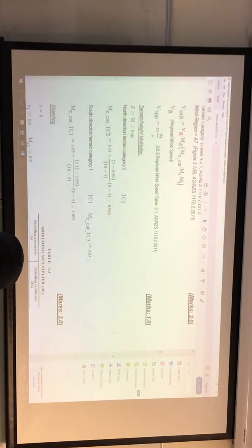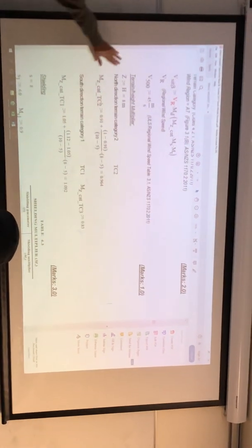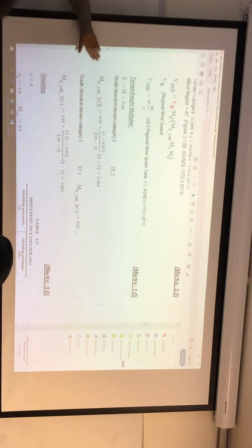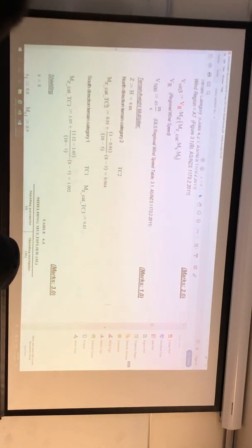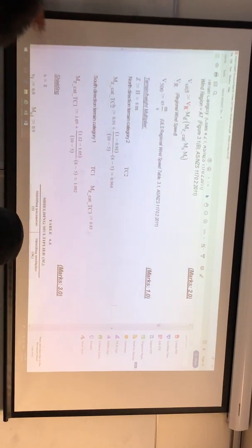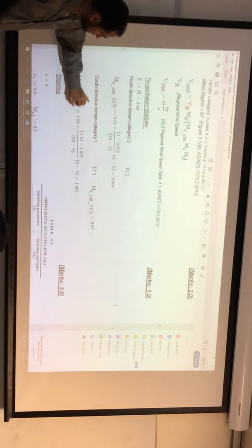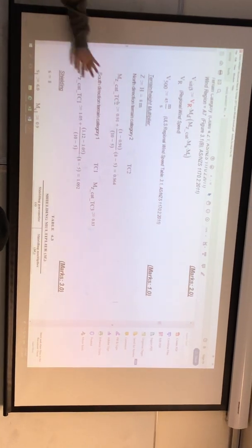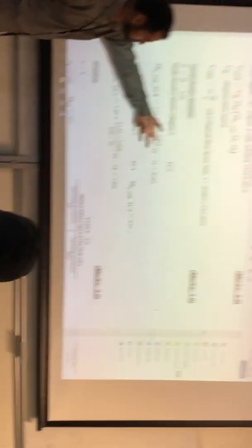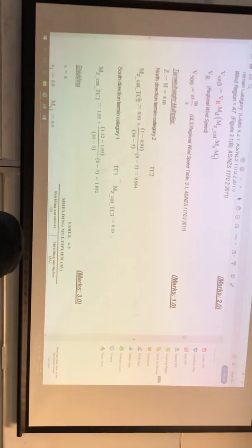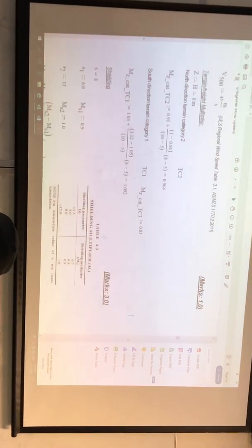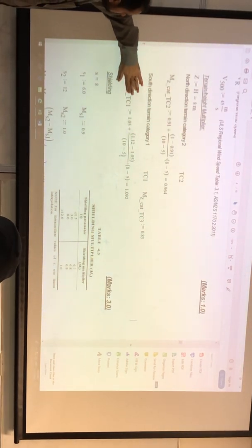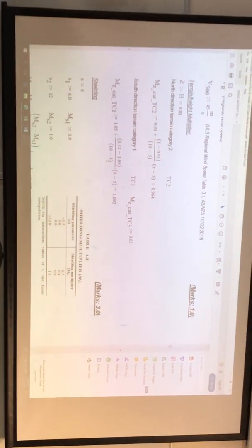Then the terrain height multiplier, again it's easier, the height is given, the terrain category is given, it's TC2. All you have to do is go to the table and calculate Mz,cat. In this case it's 0.964. And then for the other direction, because the directions are given, the terrain category should be the other way around, 2 and 1. But the numbers are right. Yeah, 2 and 1, it's okay.